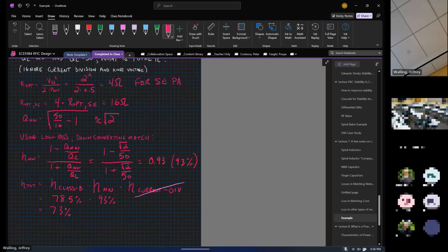Alrighty. Now, I don't know too many people that use this particular method of finding the loss in the matching network, just from the network, but I found that it works pretty nicely if you're doing algorithmic approaches to design. So I like to make MATLAB and use it to optimize things before I get into a simulator. And this works pretty well.